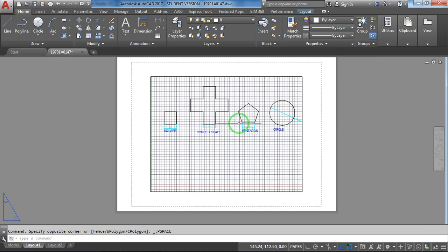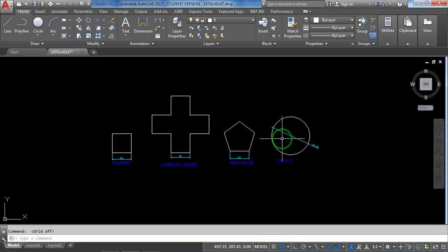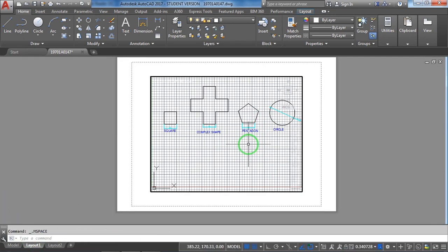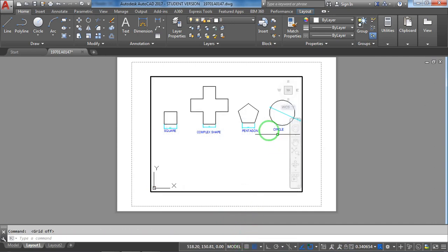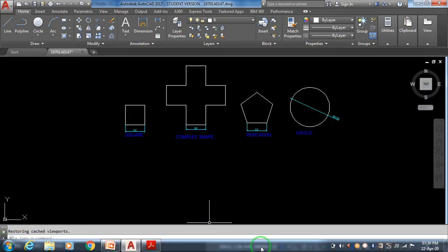They are grids. You know how to turn the grid off and on. Go to model space. You can see here snap mode, grid mode. Alright, F7. If I keep this off, you can see AutoCAD without lines. So now if you go to layout, you can see your drawings all in a white paper, something like a drawing sheet. Hope you are all clear how to check model and paper space.